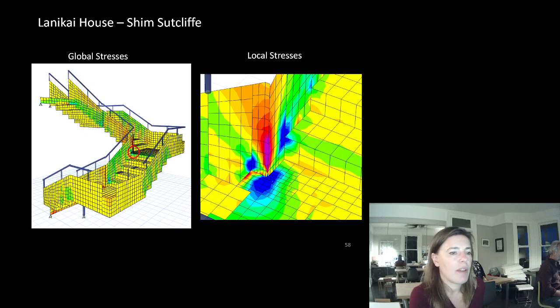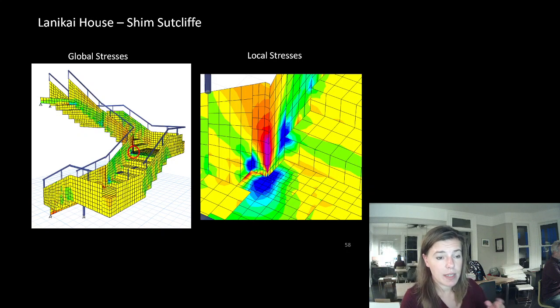If you've ever heard the stories about one of the early Boeing 747s, they had square windows in the planes, and there was actually a crash, I think more than one, because of the stresses in the steel where the glass window intercepted it, and it caused catastrophic failure of the plane itself. And so now you'll always see rounded openings in the steel for the windows.